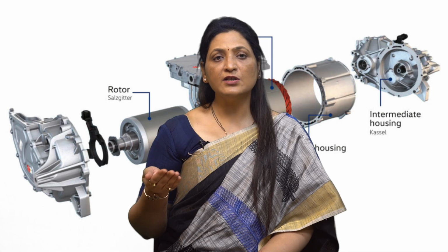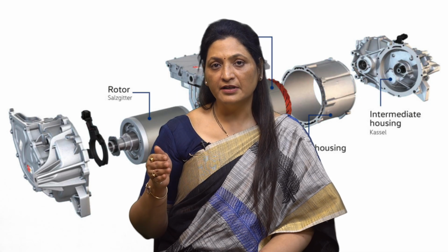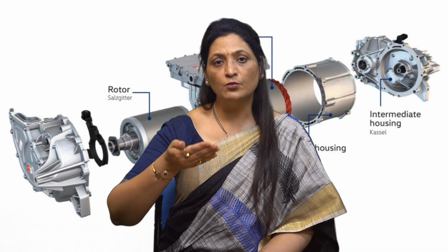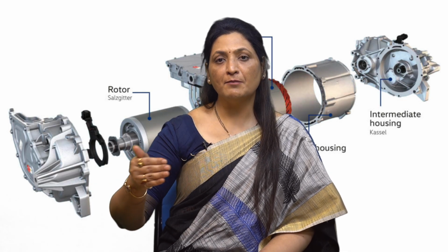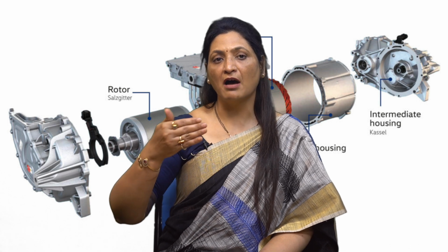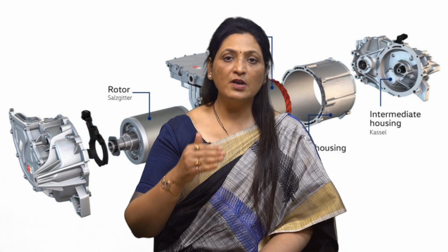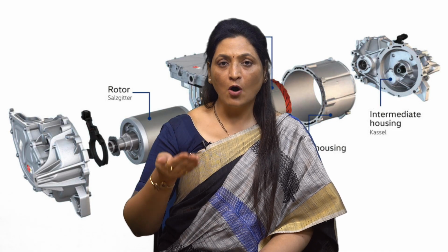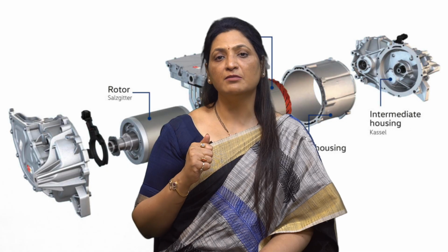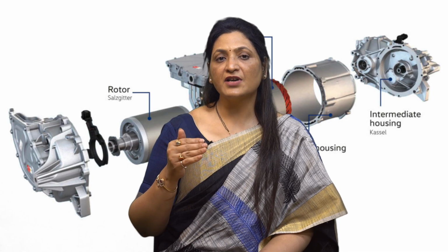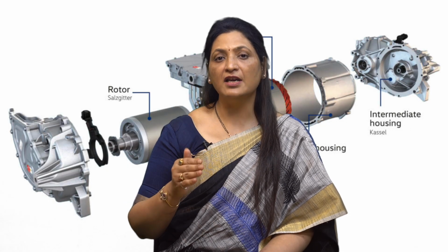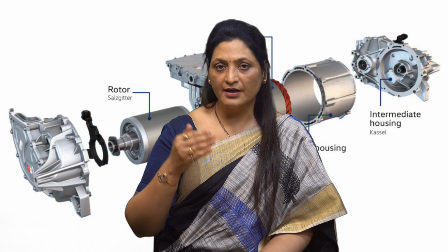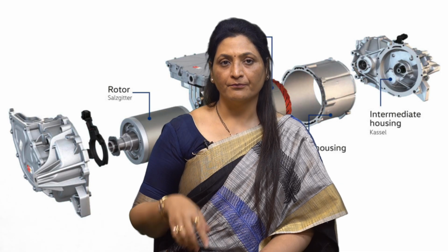Since the electrical sources are normally uncontrollable, it is necessary to be able to control the flow of power to the motor. This is achieved by using a power processor or power modulator. With controllable sources, the motor can be reversed, can be stopped, or can be operated with variable speed. Modern electric drives normally use power electronic converters to shape the desired voltage or current supplied to the motor.